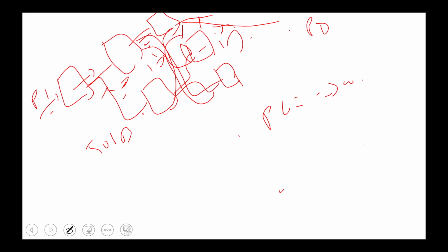Am I correct? Yes. You just play with the path which you want. You have to give a 4-port coupler at the input and the output is also 4. In between you have to give the two couplers, 2x2 switches. Select the paths, and the unwanted path will have minus 50 dB from that. Yes, that's all.